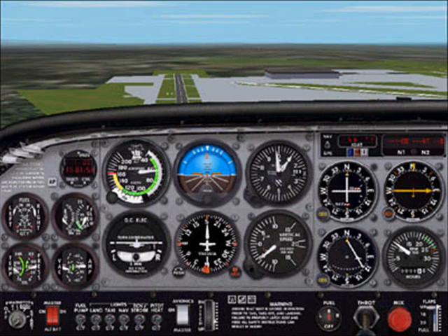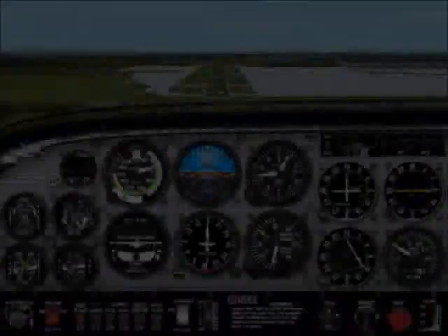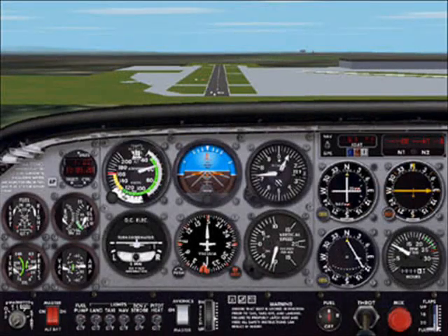Don't forget to trim. You'll apply the other 20 degrees of flaps in 10 degree increments by pressing F7 2 more times until 30 degrees of flaps are extended. That's full flaps for this airplane. As you press F7, be sure to adjust the pitch for 60 knots of airspeed. If flap usage is sufficient, you'll notice that the runway stops disappearing underneath the airplane. The airplane is also pitched forward a bit, allowing a better runway view.